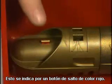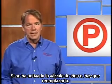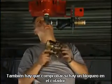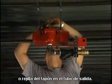This is indicated by a red pop-up tab. If the shutoff valve has been activated, it needs to be replaced. You also need to check for blockage in the strainer and in the cap screen on the outlet pipe.